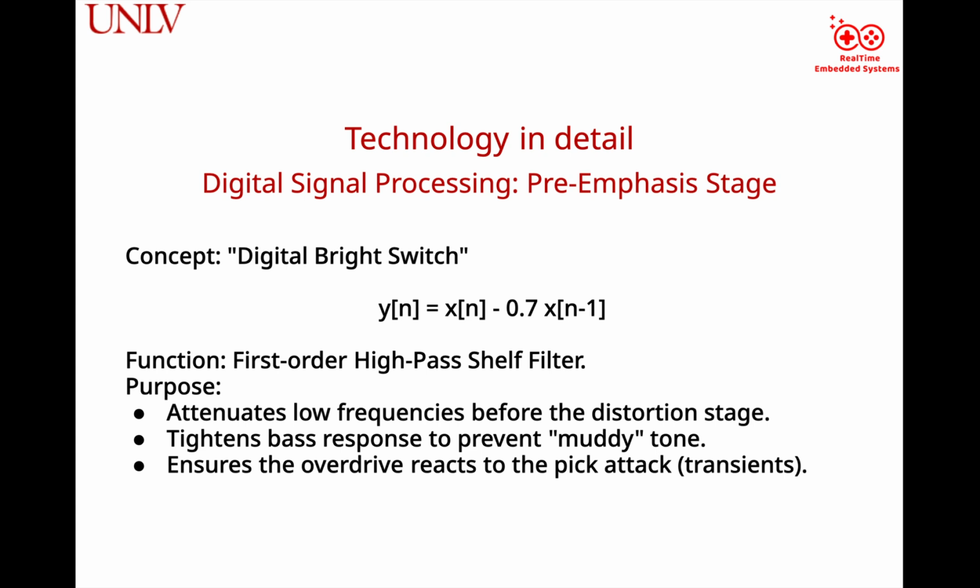So it attenuates the low frequency. Like I said, it's similar to the real amplifier, where the bright switch cuts off the low frequency and boosts the high frequency. So by using the equation y[n] = x[n] - 0.7 x[n-1], we tighten the bass and enhance pick attack clarity.